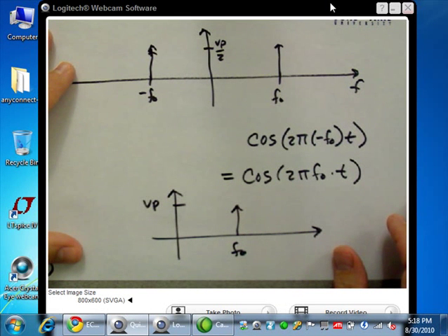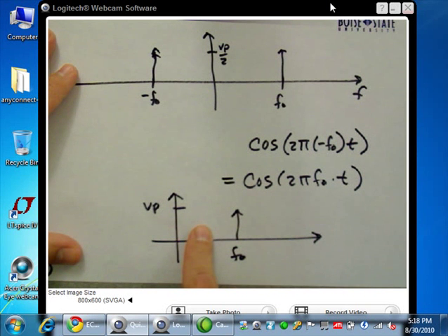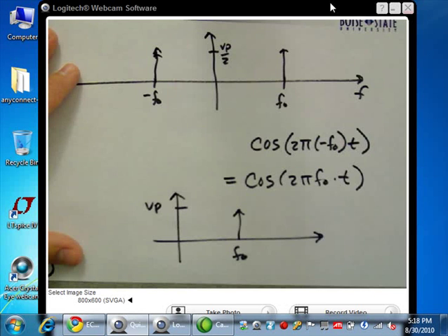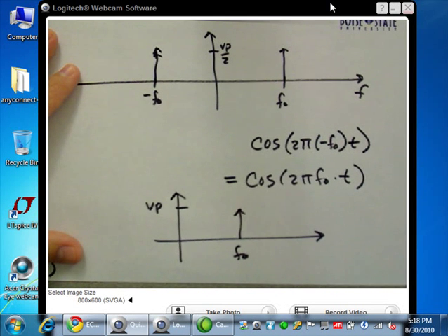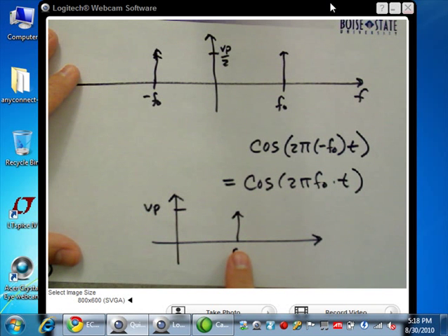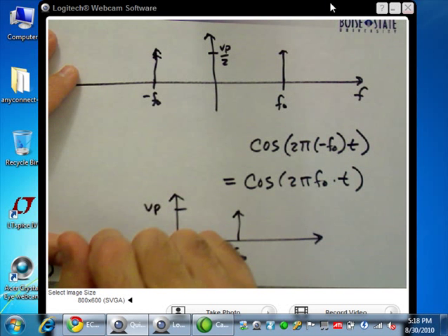I mean, if I'm looking at a spectrum analyzer, I'm not going to see both sides of the spectrum. I'm only going to see a one-sided spectrum, and it's just going to show the peak of the voltage if I have the spectrum analyzer set on displaying peak, that is. Could be on RMS. Are there any questions? So in going from here to here, I say that power has to be conserved. The reason I fold this over is that when I sum the signals, power is conserved.